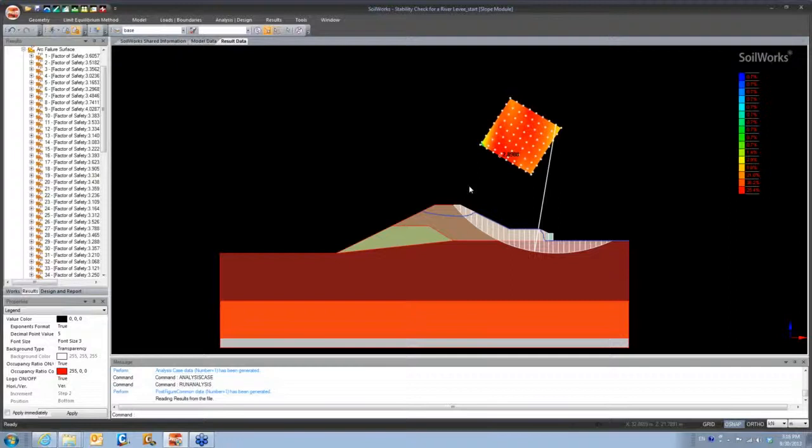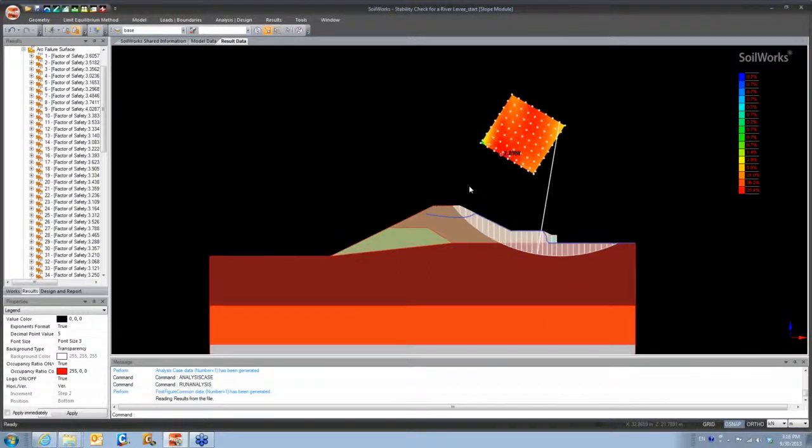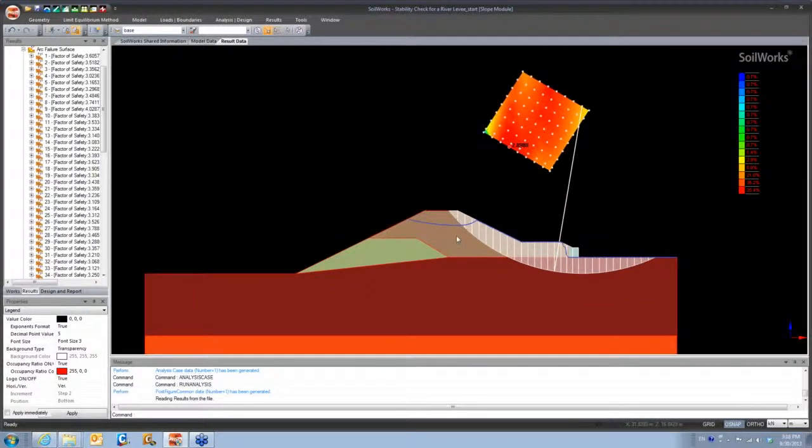It's somewhat influenced by the seepage taking place. That's correct. As you can see, it forms a curve, because the permeability changes over certain points. Based on how the water flows through the material, the water level will be different at different points.